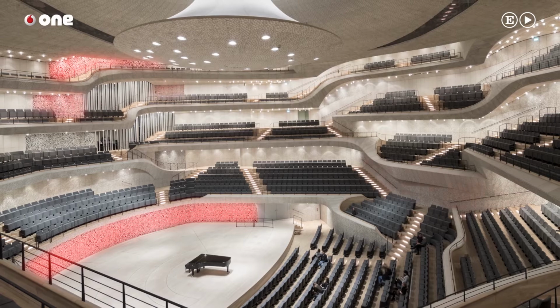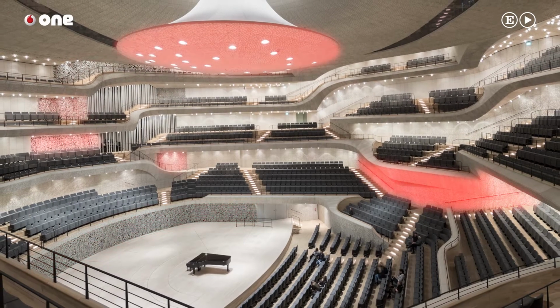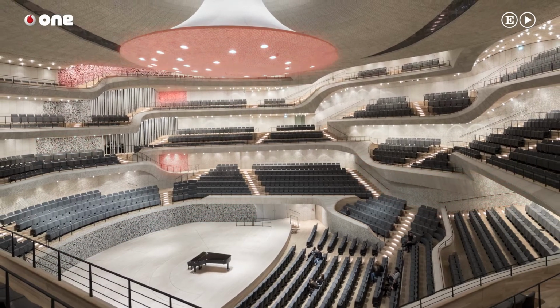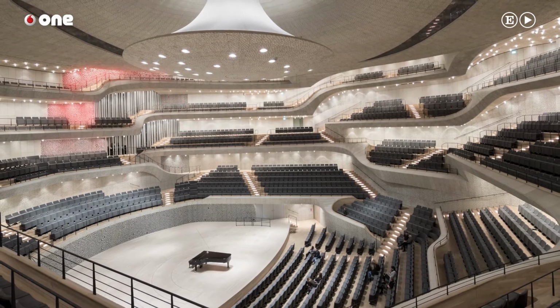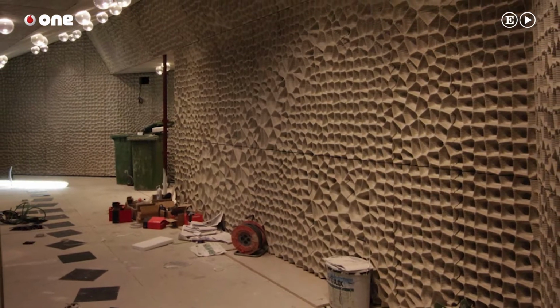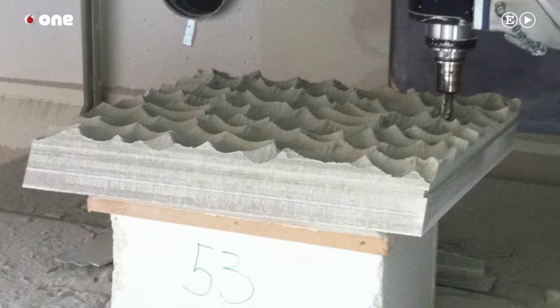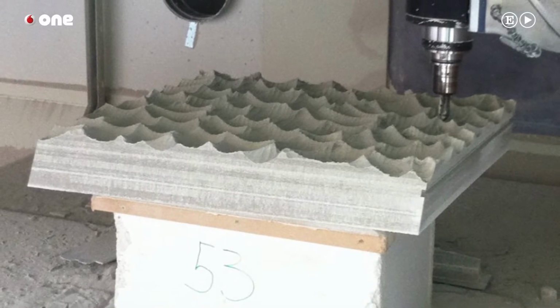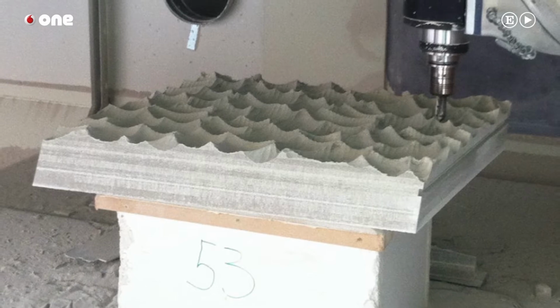And the physical part of the process involved the actual fabrication and assembly of the panels, which was done using CNC milling machines. They cut out each panel from a solid block of very dense gypsum fiber material. After each panel was formatted on the back side, it was flipped on the machine, and with a round ball head milling bit, the acoustic pattern was applied and milled into the surface.